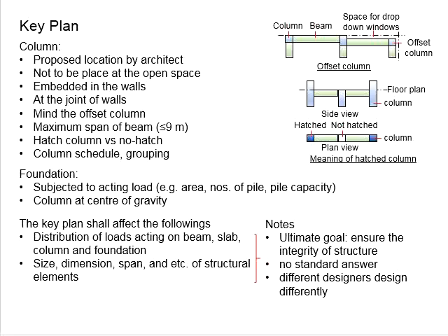You can acquire the catalogue from the internet, given by the supplier. You can seek the local suppliers for the catalogue. They have their standard sizes as well as standard capacities. Based on the range of loads acting on the foundations, you will need to decide which pile to use. For typical developments of residential, office and commercial buildings, which are less than 3 storeys, normally we will use the RC piles.